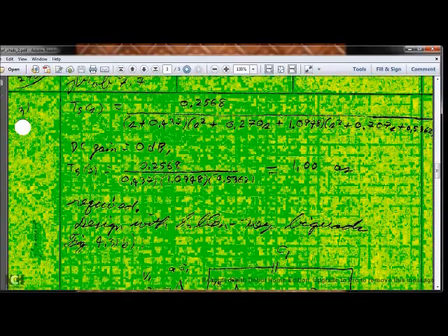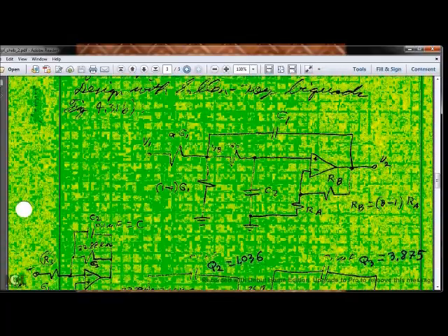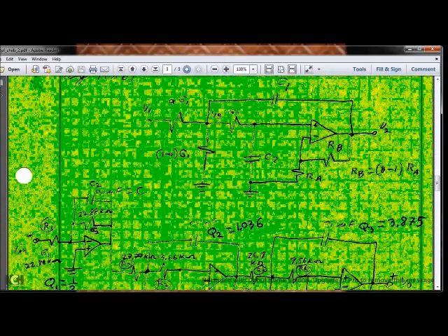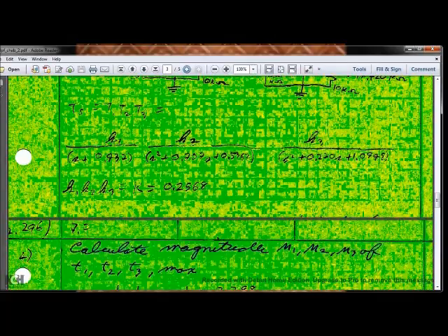So what is the gain at 0 decibel? We'll plug in for s equals 0. We get 1.0 as required because it's a low pass filter. So here we have our Sallen-Key biquad configuration. And T5 is equal to T1, T2, T3. We split the transfer function up into 3 factors with a k in the numerator and a polynomial in each denominator. And k1 times k2 times k3 is our capital K.